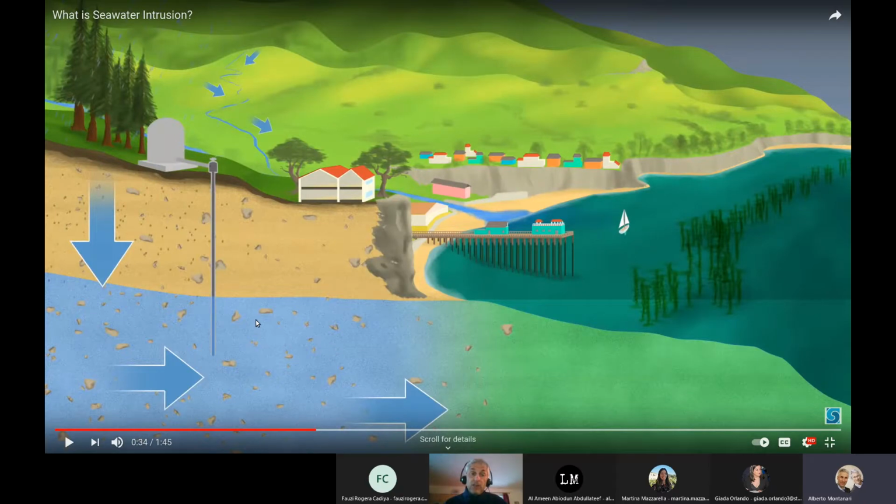Groundwater flux actually occurs in coastal regions very frequently because coastal regions are often characterized by permeable soils. In permeable soils, you have infiltration. Infiltration means groundwater replenishment and groundwater flux to the ocean. Actually, the amount of water flowing into the ocean through the underground is very considerable. It's something that we don't see, but it's very important.